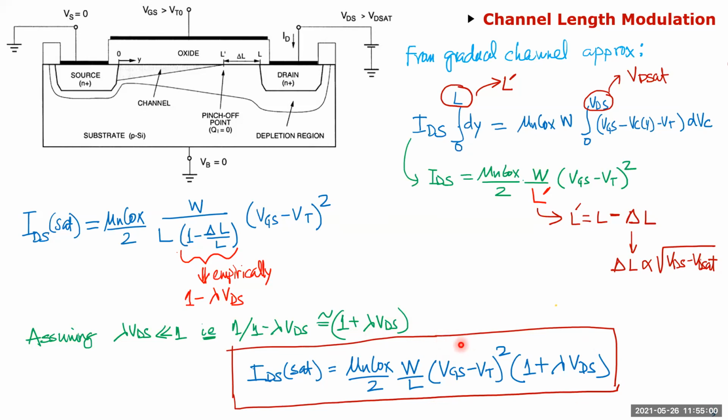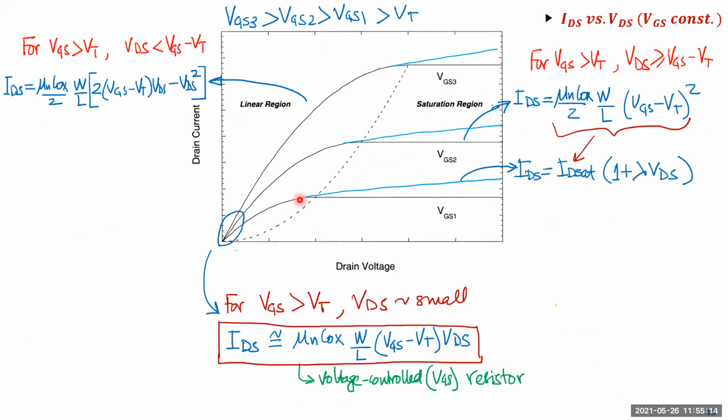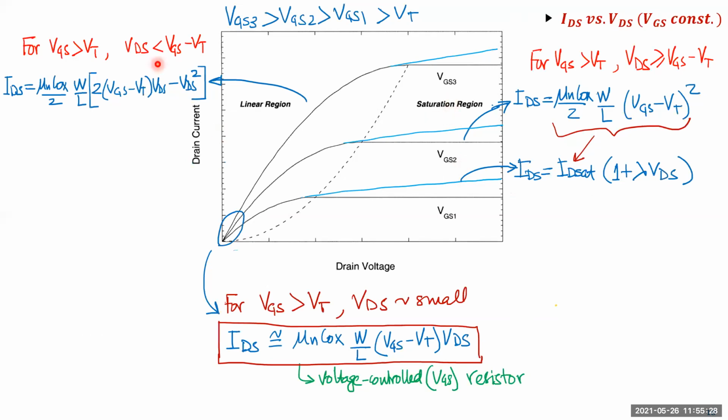And like I said, in analog design, even in a lower node, we use longer channels most of the time, so these equations are pretty much always valid. So if I make that correction to the summary I showed last time, now instead of remaining constant, it's going to slowly increase linearly with VDS, and that term is the adjustment here, and gives you an intuitive reason on why it's changing. Okay, any questions so far?